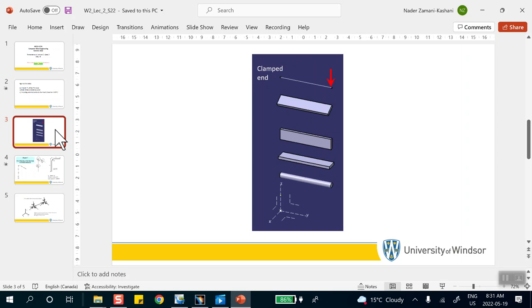But remember, when you draw a straight line, if, for example, my cross-section is rectangular, such as what you see here, you don't say how the cross-section is oriented. For example, if I make that cantilever beam from that orientation on the second one from the top, or the third, or the fourth, they all deflect differently, okay? The only thing that doesn't matter is a circle. Circle, it doesn't matter how you turn it.